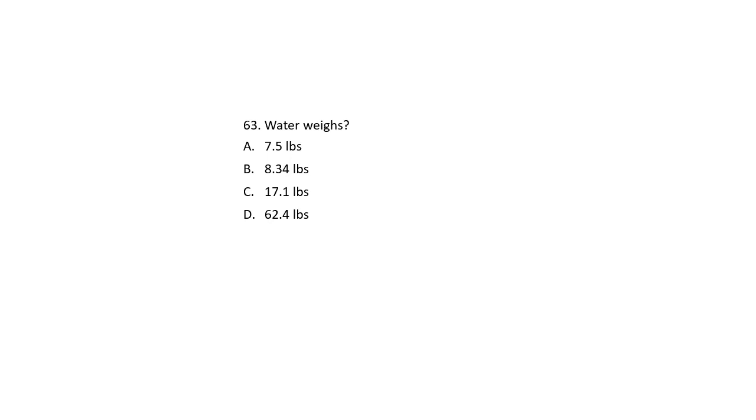It's used for hardness. The grain per gallon is the unit of water hardness defined as 1 grain, 64.8 milligrams of calcium carbonate dissolved in 1 U.S. gallon of water. So that's where you get the 17.1 parts per million. Also apparently called the Clark degree in terms of an imperial gallon. And a cubic foot is 62.4 pounds. Those numbers sound familiar. That's why, again, a lot of times you will have a formulation sheet when you're taking the test.